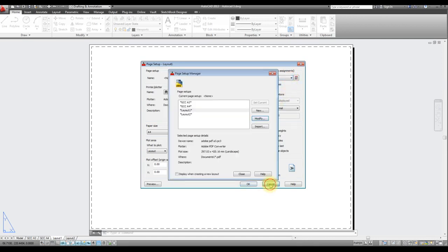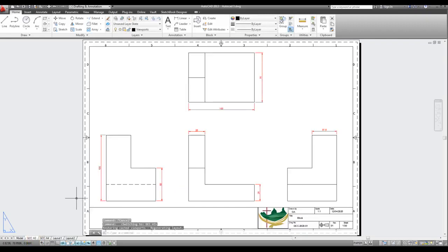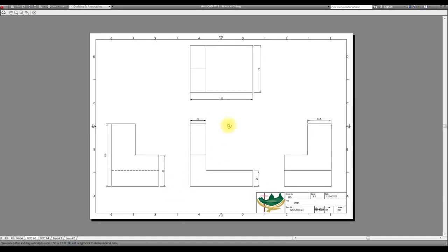The issue with that, what becomes evident when we print these, is that you've got to have a print setup so that when you click print, we don't want these to have red dimensions. We want everything to be black and white on the page except maybe your logo and the dialogue in the title block. Go to preview, you'll notice all the dimensions are the same.